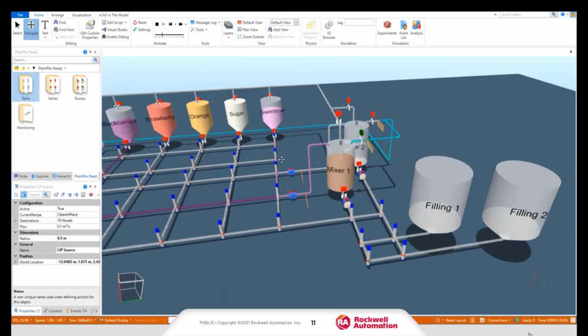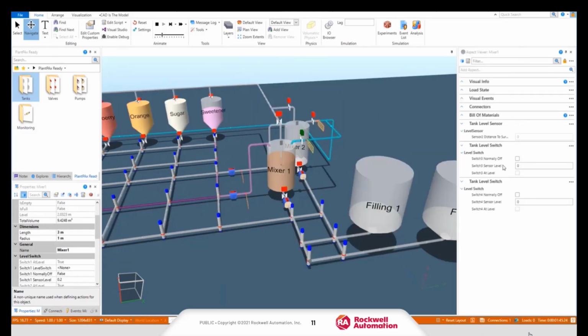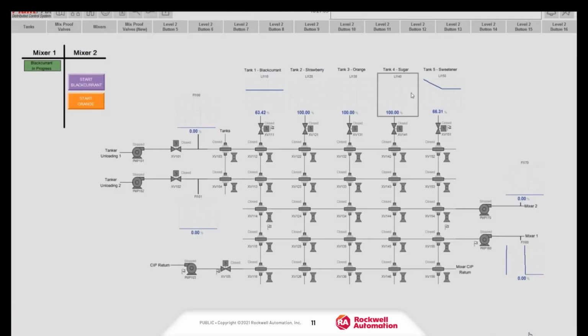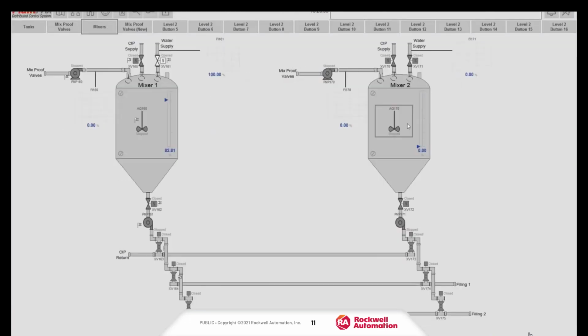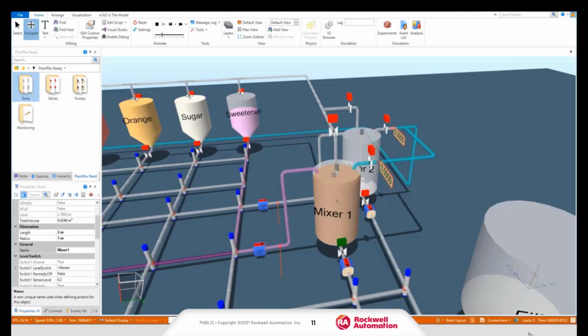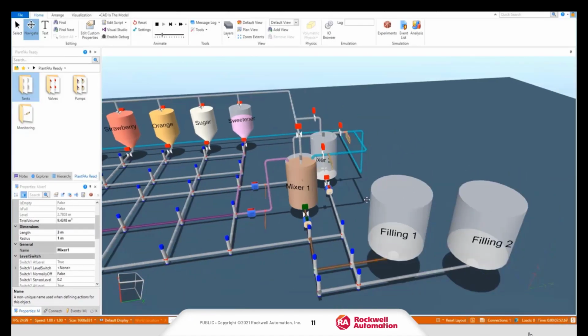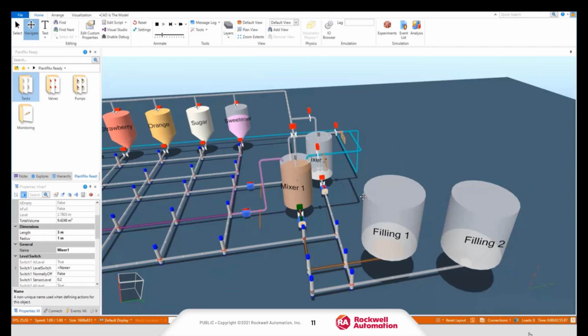So for basic controls testing, we can first of all see if our system behaves as we anticipate. This is a validation that we've written our cycles correctly. And this will obviously include things like clean in place as well, so producing a longer cycle. What's interesting is this additional testing that's possible, these fault conditions that we can conveniently introduce inside Emulate3D.